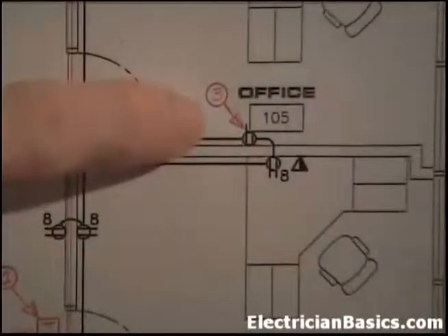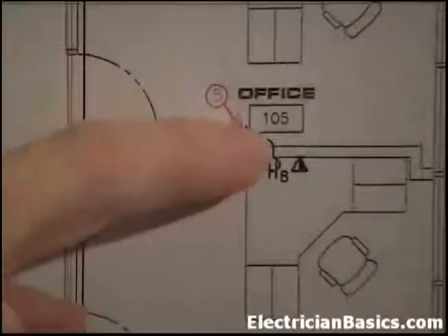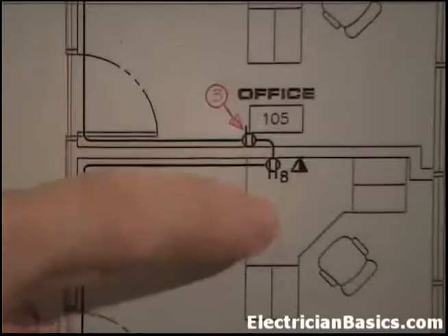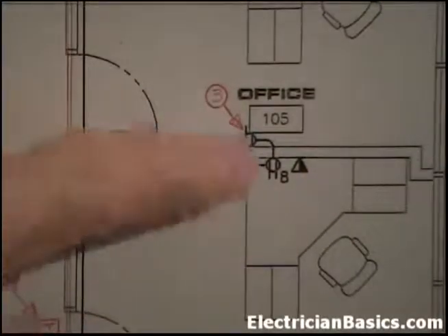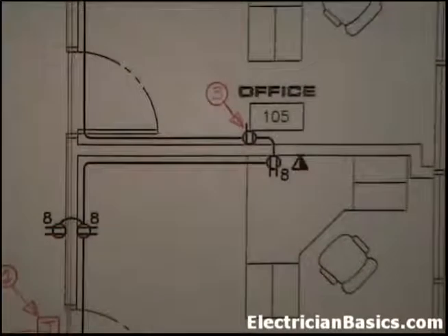Okay, the reason I have a red line right there is we don't know what that circuit is, because it looks like it's covered up by that room number. It could be 8, but if you take a wider look and go up here, it's circuit 10. And we have on our home runs 8, 10, and 12. So let's try and figure out a way to determine what that circuit should be.